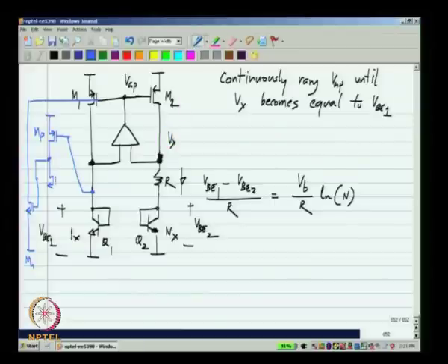And that can be ensured by connecting it up like that. Essentially, we have a CMOS inverter structure here. So, if this voltage reaches a sufficiently high value, which is about 0.7 volts or so, this transistor tends to pull this node down and deactivate Mn.